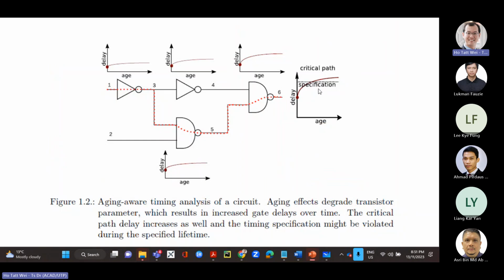first. And of course, because you know about process variations, you also know that it's better to not just apply this on the critical path, but also apply this analysis on the near critical path. It means this type of analysis on aging is useful not to apply to the whole circuit, right? Because the whole circuit will age, but you're mostly putting your attention on, again, the critical path and the near critical path, because the effect of increasing the delay of these two paths is more catastrophic than in other parts of the circuit.